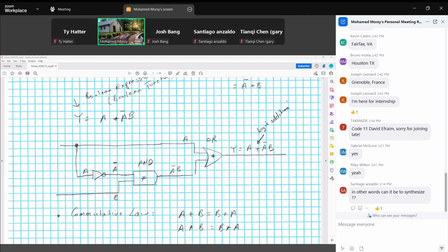This is called sum of products. We'll talk about this in detail. And always, if the output is sum of products, the output gate used is the OR gate, because OR gives us logic addition between the terms. Between this term and this term, we have logic addition, not multiplication. So definitely the gate we draw here is the OR gate.